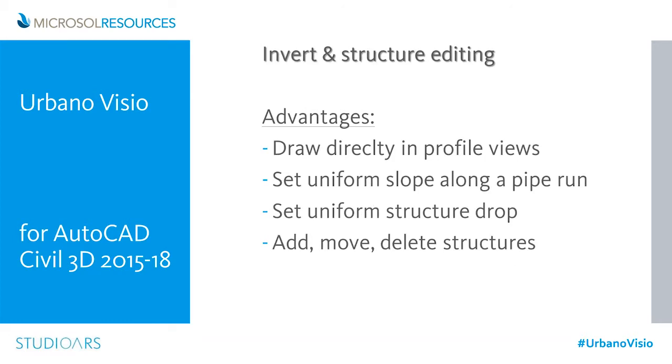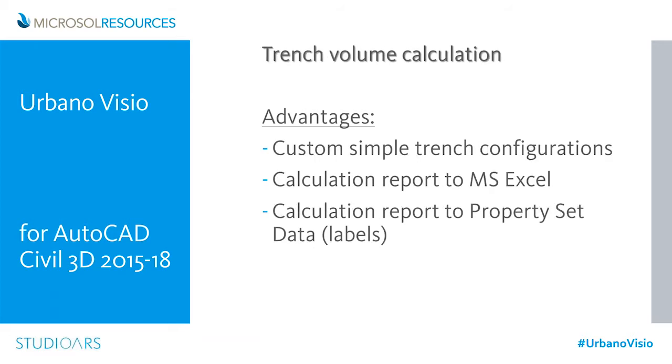Okay, structure editing. A few things, I will be showing all of this, so you can draw directly in profile views. Sometimes this is quite handy. You can set a uniform slope along a pipe run. You can set a uniform structure drop along a pipe run. And you can add, move, and delete structures directly in profile views.